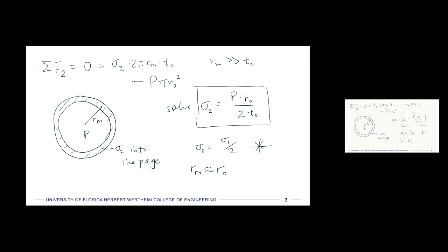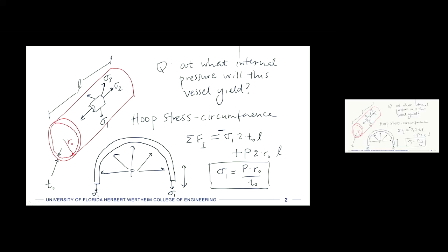And then there is a radial stress, which I failed to mention, in sigma 3. We go back to my picture here. And sigma 3 doesn't actually have a very strong value at all in this situation. So we're going to say that sigma 3 equals 0, and that this stress is happening in only the sigma 1, sigma 2 direction. So it only happens in the plane of the pressure vessel, and it's not happening through the thickness of the pressure vessel. So now we have 3 values of stress. We have our 3 principal stress values. Okay, so far so good.